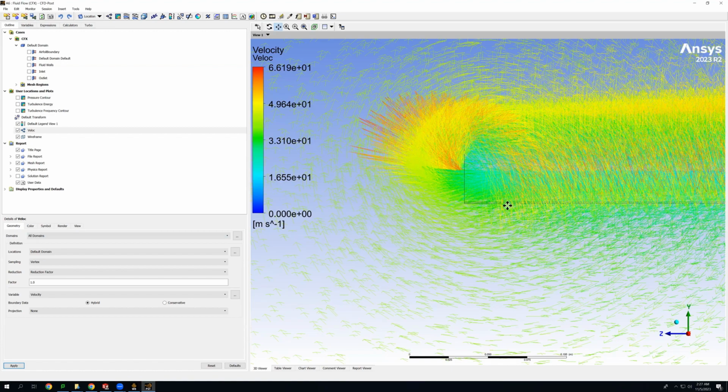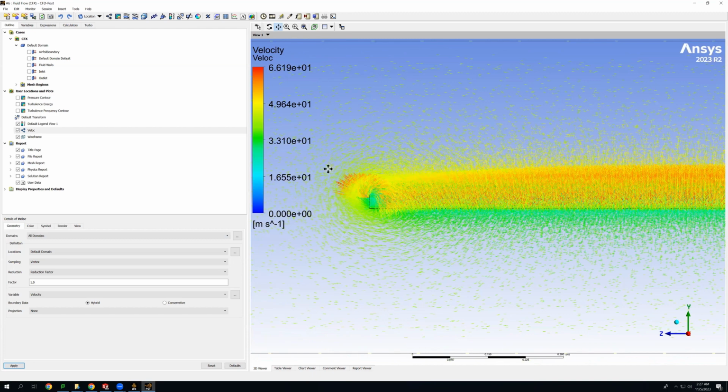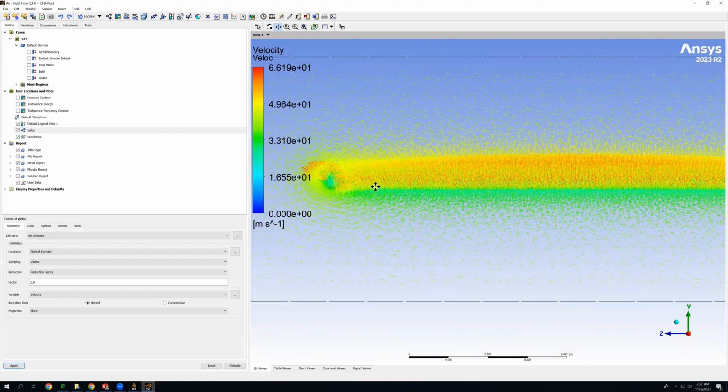And as you can see, there's kind of some missing arrows in this section. So this represents where that turbulence is, because the air creates a gap and it wants to fill it. As we can see, this spiral effect seems to mostly stop by this point, and even at this point, the arrow is at very low magnitude pointing downwards. And this represents simply a small fraction of our wing, so we can judge that it has a high enough aspect ratio for this simulation.